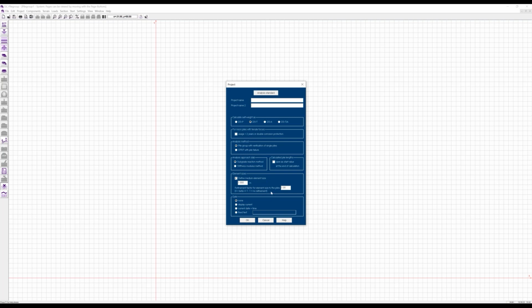In former times, it was better to use smaller elements near the support, near the piles. But this is rounded automatically, so we don't need a different factor than 1 for the refinement anymore. You can leave this with a value of 1, and this makes analysis much faster than if you use very many small elements.